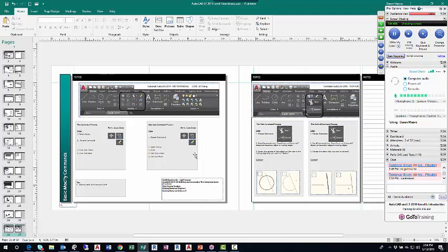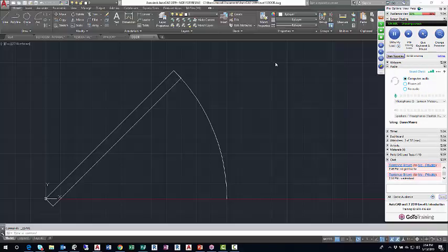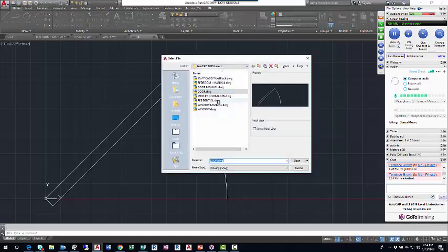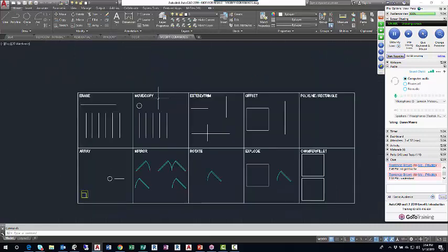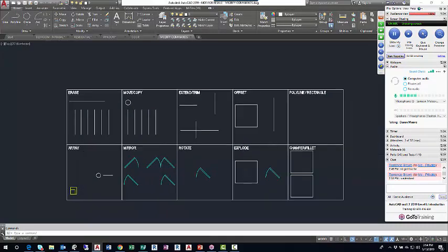If you select the command first and then the object after, there's an unintuitive step of pressing the enter key to move forward in the command, and it doesn't tell you that. You just kind of have to know. So when possible, I'll select the object first. In AutoCAD, I'm going to click Open, and one of the drawings I supplied to you, I hope you have it, it's a drawing called Modify Commands. So if you can find that and open it, that'll be great.